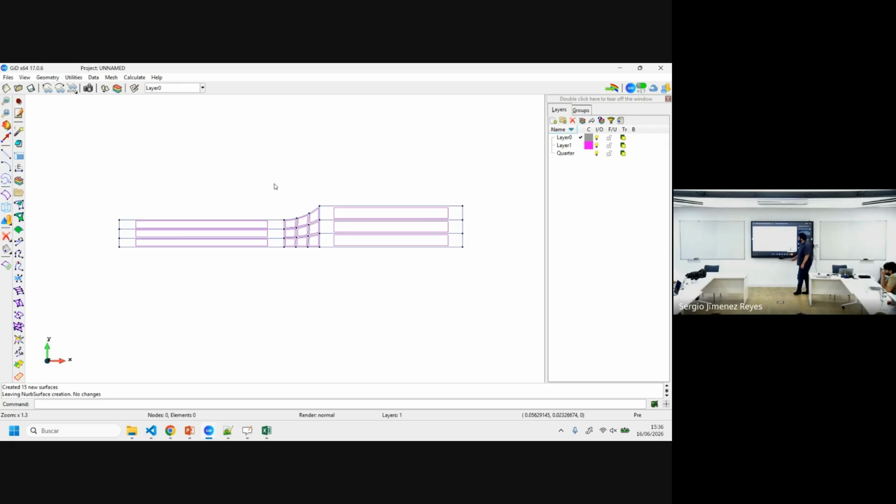In our model, what we are inputting is the behavior of a point. Okay, but this point here will not behave like this point here. Okay, that's true. But because the type of test that we are doing is a tensile test, and the stress distribution results in a pretty homogeneous stress state in all this section here, using a calibration which more or less matches the experimental data will result in a pretty good calibration of the model.